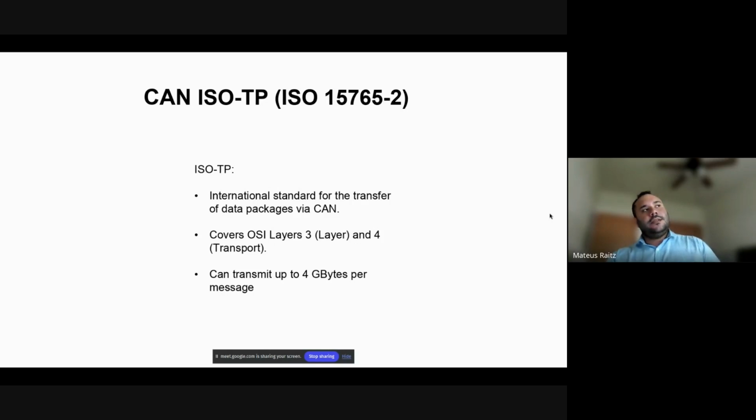But it actually is using CAN 2.0B or CAN FD in the back. It's just dividing a large data into different CAN frames and then combining that together. It's doing something similar to what the micro-ROS client and agent are doing.